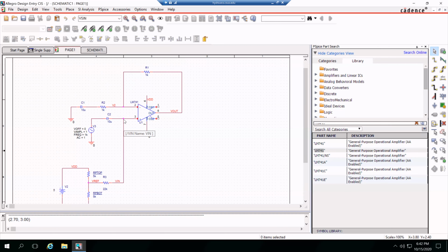What's the pole frequency? So the pole frequency kind of tells us at what frequency we need to be above in order to get the circuit to perform right. And you have two conditions, right? You have this pole frequency and you have this pole frequency. So this one up here is easy. It's just 2. This one's a little more complicated because you got the 22K ohm and the potentiometer. That's why we simplified it and we figured out what the impedance is looking down through VN.